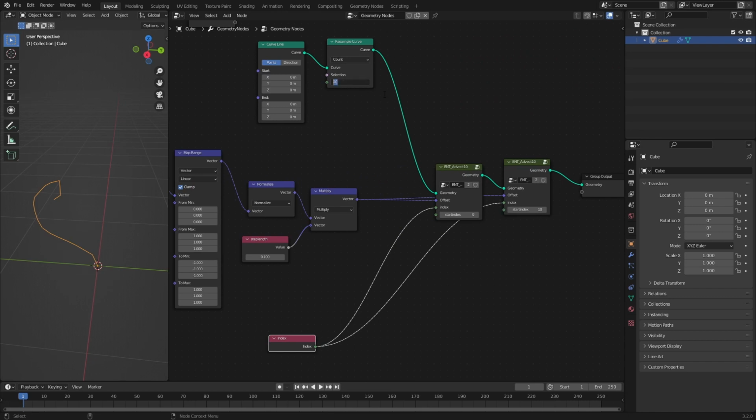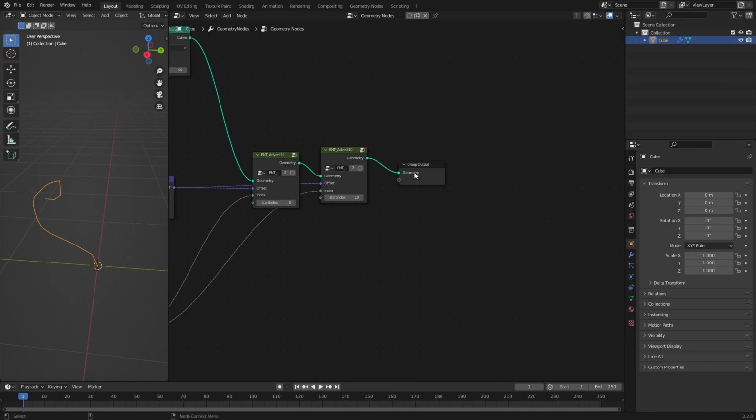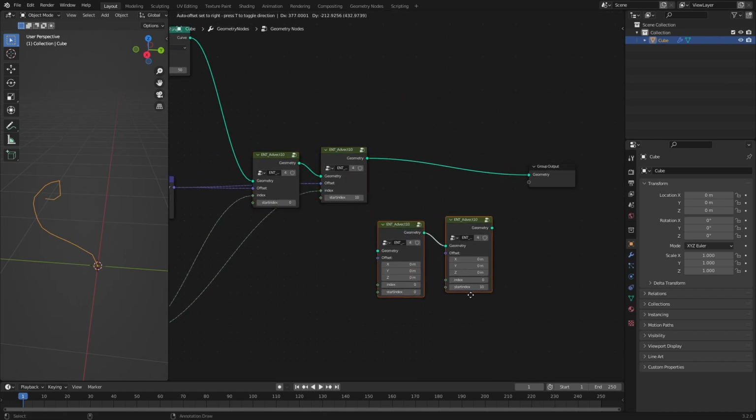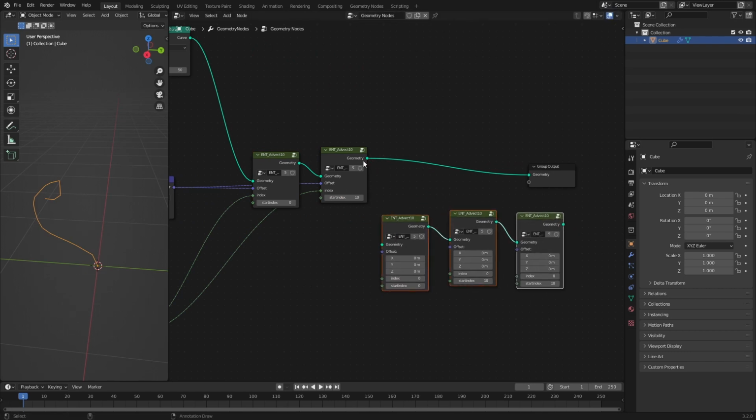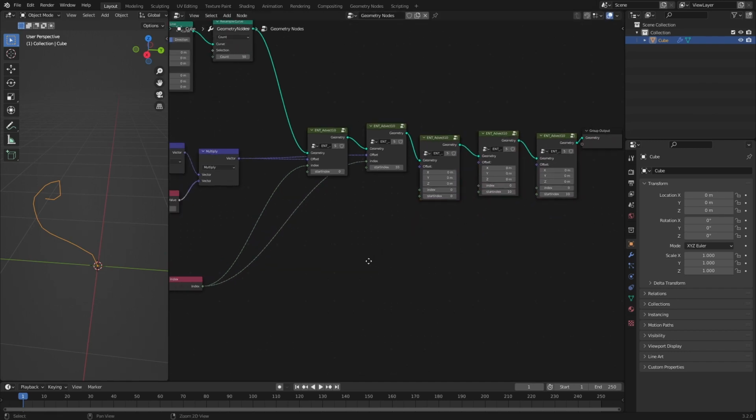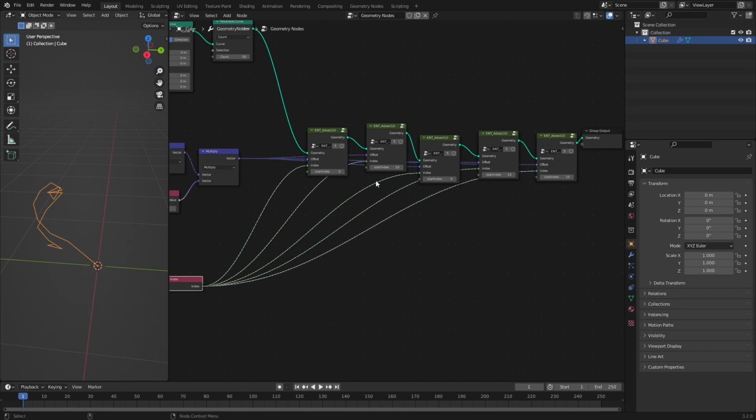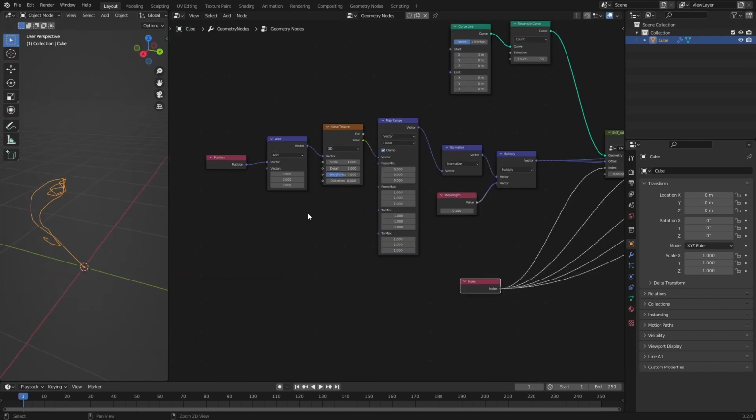So let's go to 50 points, and let's just duplicate our iteration 3 more times, like so, effectively creating 50 iterations for 50 points. Connect everything up, and before it will start to work, we have to first give every node the noise field, like so, and every node needs the index, and now we want to start at 20, at 30, and at 40. And now we have a spline traveling through the noise field with 50 points.